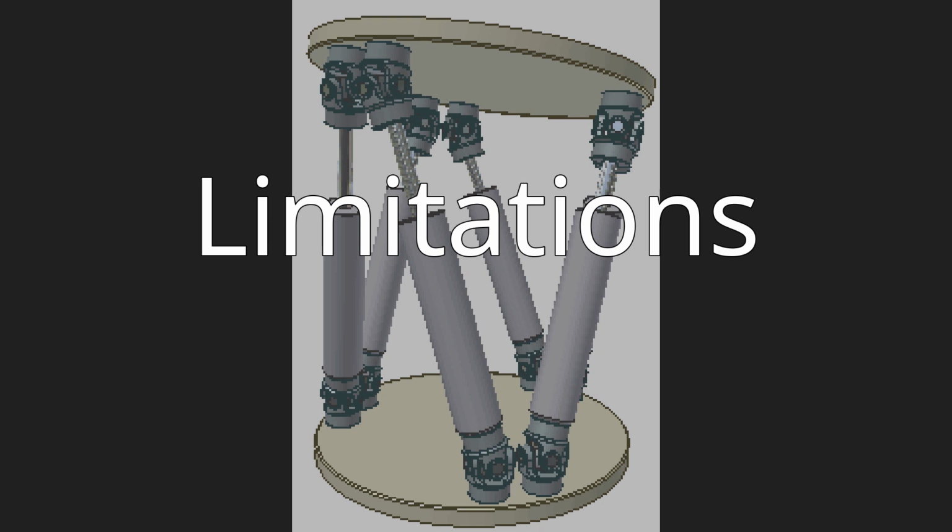This type of response only occurs if second or third order high-pass filters are used. Tilt coordination angular rate and tilt coordination remnant: for sustained specific force input in sway or surge, the simulator will achieve a steady state pitch or roll angle because of tilt coordination.